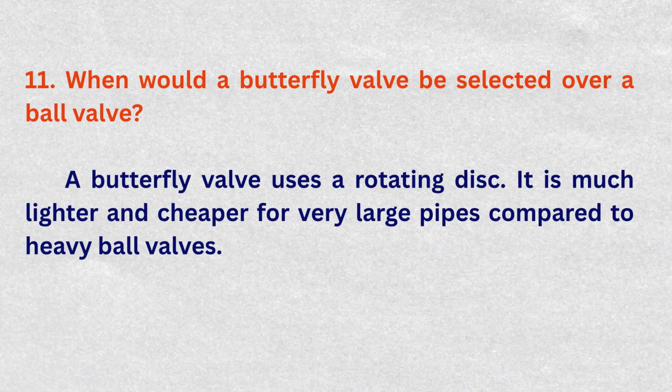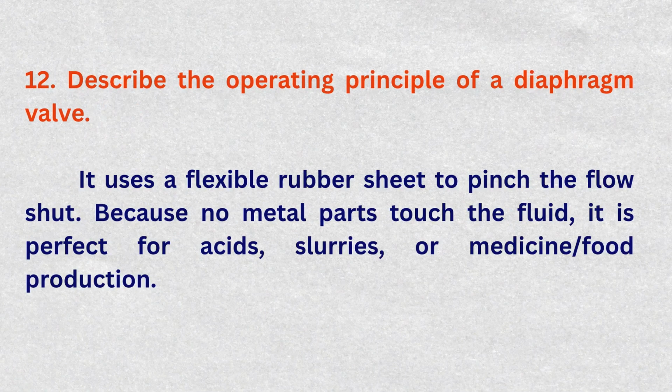When would a butterfly valve be selected over a ball valve? A butterfly valve uses a rotating disc. It is much lighter and cheaper for very large pipes compared to heavy ball valves.